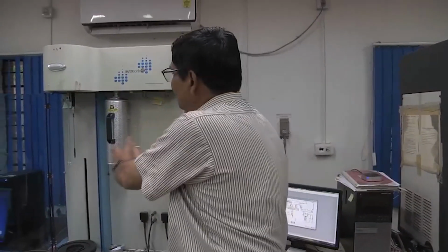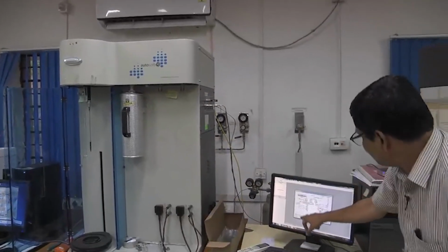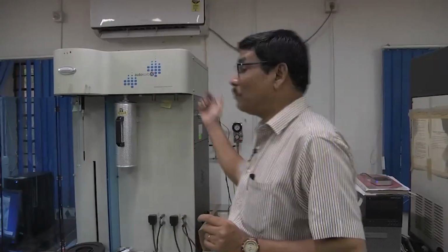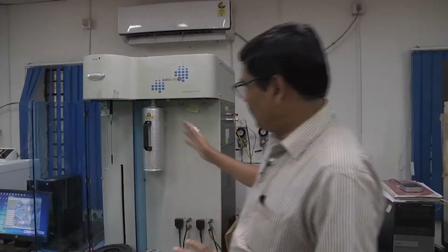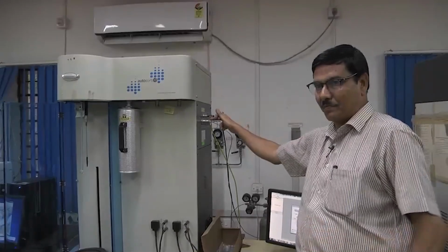So, now how does this analysis get done? Once your degassing is completed, you fit the sample into your sample station. After putting it into the sample station, first of all this section will be cleaned or purged by a purging gas, generally helium gas. Helium gas is used as a purging gas to clear any other vapors or gases inside the cell. After purging, there are two ports for adsorbate gases.